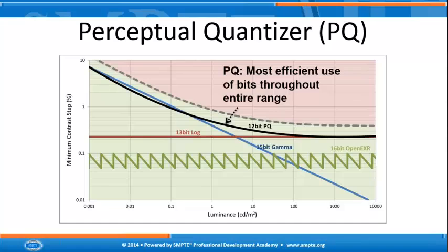And like I say, we got the plots I showed before, which showed there were definite preferences, and I'll talk about white levels in general because that's maybe the more interesting point. People were very willing to go to, let's say, 1,000 nit white level, or even 2,000 nits for outdoor scenes. This is like scenes of a glacier or things like that in the snow. They were very happy with 1,000 or 2,000 nits, even in a very dark room, which was a little surprising at first. But yeah, you adapt very quickly, it seems.